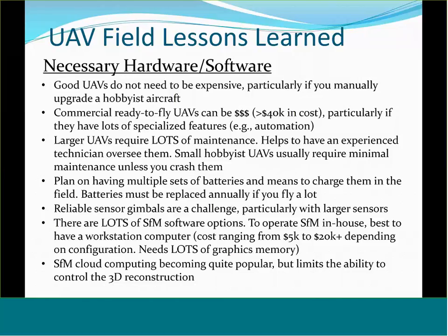Batteries tend to be the governing issue in operating UAVs in the field. We recommend you have multiple sets of batteries on hand and that you have a means to charge them in the field. If you're flying a lot, we recommend you replace batteries at least annually, otherwise the batteries can just die without notice. That happened to us once. We had a platform 200 feet in the air, the batteries just died, and the platform crashed, and we lost both the sensor and the platform.